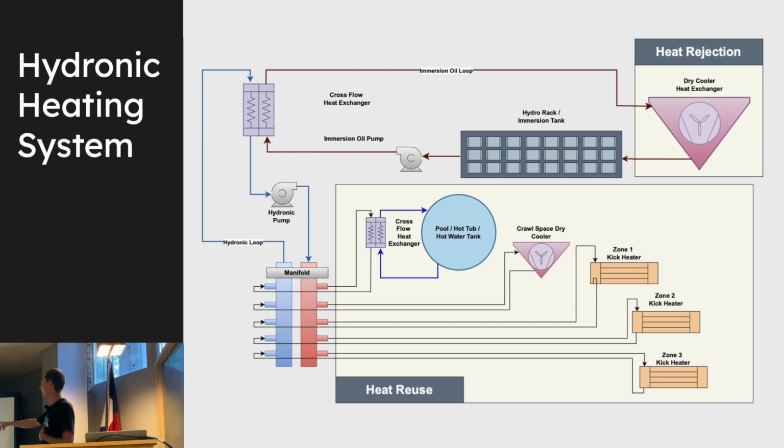And then the control part of this is, okay, what if I didn't use all the heat? So it's cold out, but it's not cold enough for me to use all the heat, right? But I don't want the miners to overheat. So if I didn't use all the heat in this first heat exchanger, and I don't use it for all my zone, maybe it's 30 degrees out and I designed it for -10, then some of the heat is still going to go back to the miners. And you have to cool it off to their desired inlet temperature or they'll overheat. So here you have an external dry cooler. And this is where you would take that heat and dump it outside, whatever you didn't use.